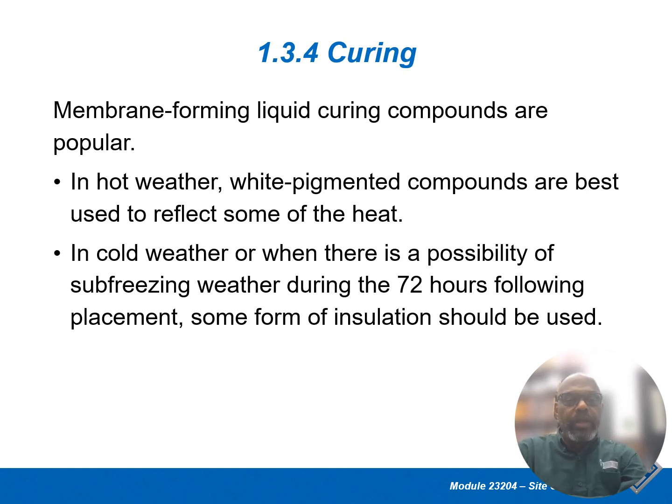In cold weather, when there is a possibility of sub-freezing weather during the 72 hours following the placement, some form of insulation should be used to help hold in some of the heat. Again, I've seen them putting just about anything over it sometimes. It might be burlap sacks. Certainly you can use things like straw, because concrete itself, as it's curing, generates some heat. But you want to make sure that it stays above a certain temperature so it can cure correctly.